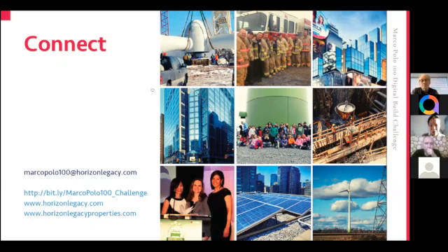Okay, so next question is from Ed. Again, does the Ontario Code require fire suppression in all concrete multi-unit construction? Secondly, is a wet sprinkler system required? So I think I'm going to direct this to Andrew. So Andrew, does the Ontario code? Yeah, the answer to the first question is yes, and I would recommend a wet sprinkler system. That would be your most cost effective and easiest to maintain. Okay. So, sorry, Andrew, you're saying in all the units?